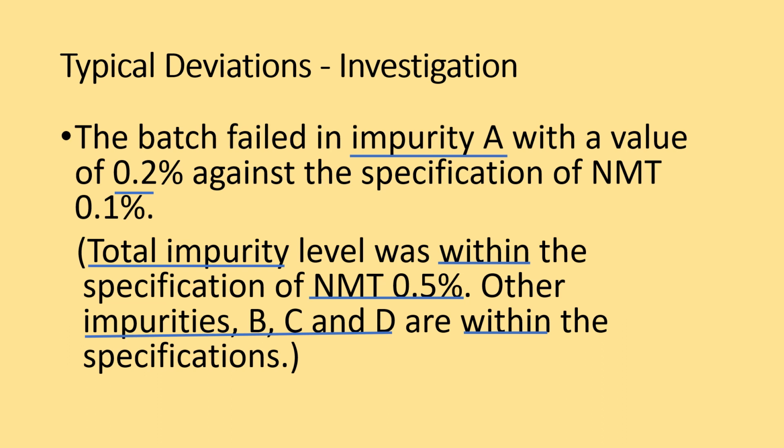Certain impurities may not be removed because of incomplete or improper washing of the product cake in the centrifuge. This also should be a part of investigation. So the investigation should look into the washing operations also. In several cases, drying operations also could significantly contribute to increase of impurities. It is necessary to confirm whether there was any excessive drying that could have caused the increase of impurity A. So the investigation should revolve around the actual culprit of the failure.